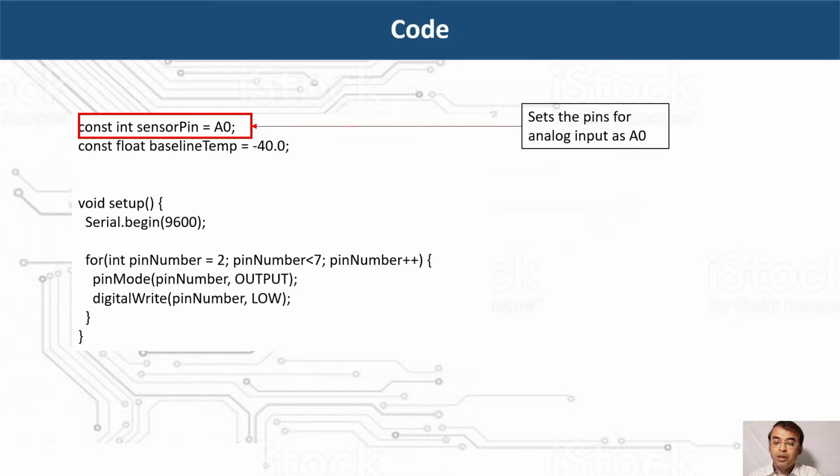Now I have initialized all the output pins, the LED output pins, which are basically the anode pins. You can see from 2 to 6, there are 5 output pins for LEDs. I have used one loop starting from 2 and ending with 6, that is why there are 5 pins. These are the output pins, and we have initialized them to value 0, or low.